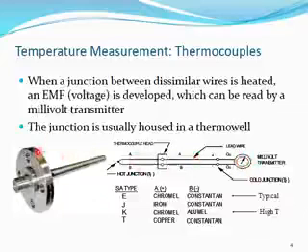And this one is the thermowell, the device that should be inserted in the place in which you need to measure the temperature. The thermocouple is inserted inside the thermowell. These 2 dissimilar wires come in different types, for example E, J, K, and so on, and every model depends on what type of wires we have.